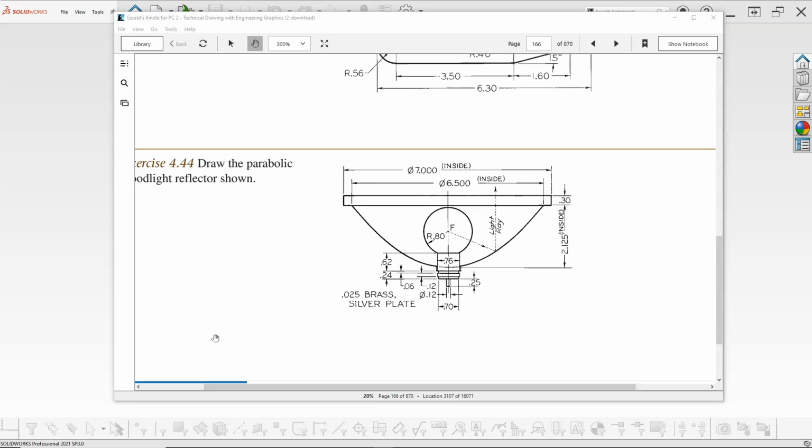Okay, the parabolic light, we're going to have the geometry. Typically this would be a revolve. We'd have a little bit of a thickness, whatever this geometry is, whether it's stamped and polished or some kind of geometry. And since this would be a revolve, we would draw half of it and then revolve it around. Or we could, since we're focusing on the sketching, we'll just draw in the same fashion, except that we'll go ahead and mirror.